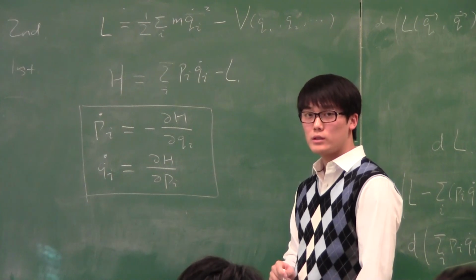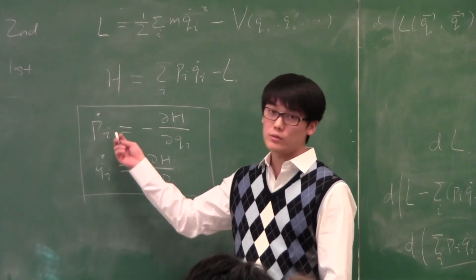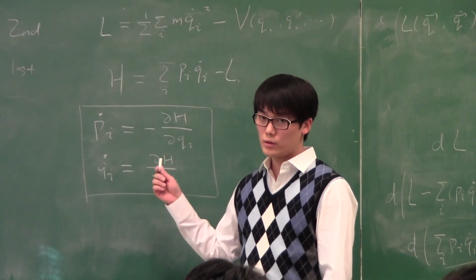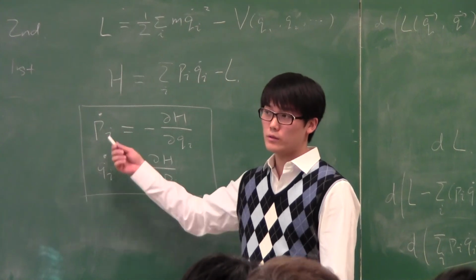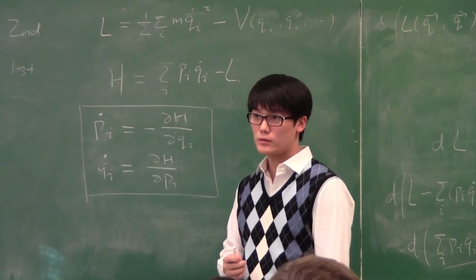And now what is good about these equations of motion is that we have achieved order reduction because both of them are first order in time. But to do the order reduction, of course, we have doubled the number of unknowns. So this is the Hamiltonian formulation.